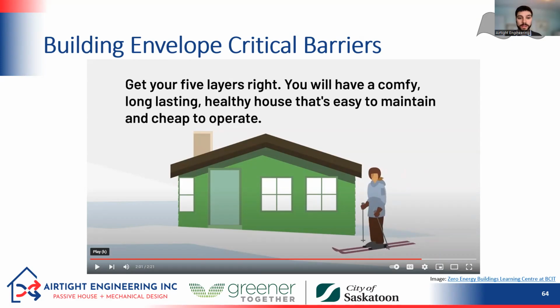Another really key one is airtightness. You can actually lose up to 30 to 40% of the heat from your house due to poor airtightness. So you might have added all the insulation in the world, but if your house isn't airtight, it's not going to be efficient. And so we certainly need to make sure when we're talking about home energy efficiency that we have a basic understanding of these five critical barriers and the roles that our building envelope is playing.